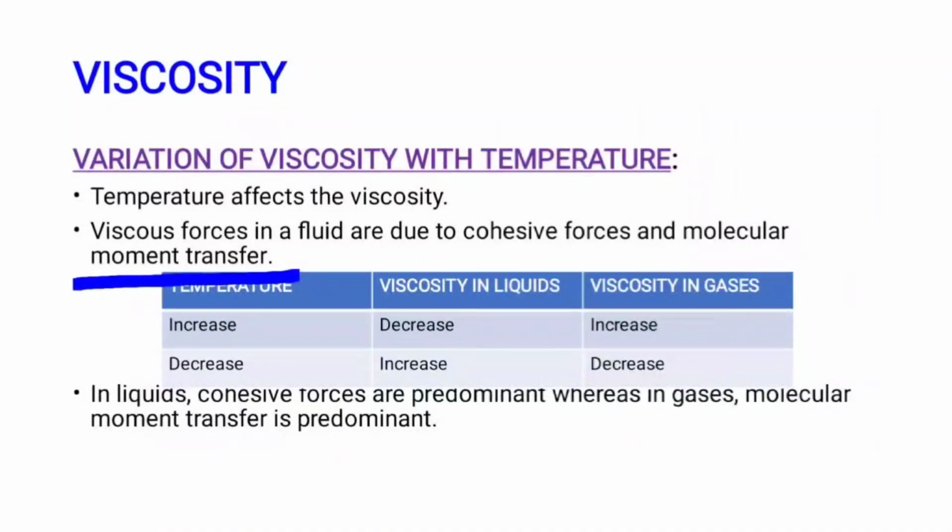And molecular momentum transfer. If temperature increases, viscosity of fluids, how does it change? Fluids are liquids and gases. In liquids, cohesive forces are predominant, that is, cohesive forces are more than molecular momentum transfer. Whereas in gases, molecular momentum transfer is more than cohesive forces.